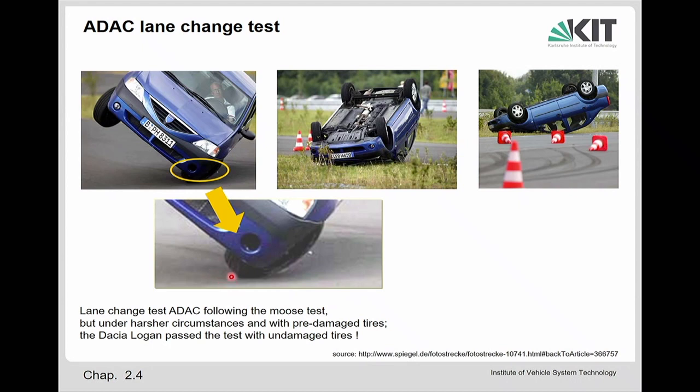Normally the contact should be here, but now the contact is here on the side of the tire, and there's a completely different rubber, and this rubber on the sidewall is more soft, and it creates a higher friction coefficient. So in this moment, not only the end stop creates this extra vertical load, but also the side wall of the tire creates a higher friction coefficient. And then this rollover starts. It is similar to when the car hits the curbstone and it avoids a further sliding. No?